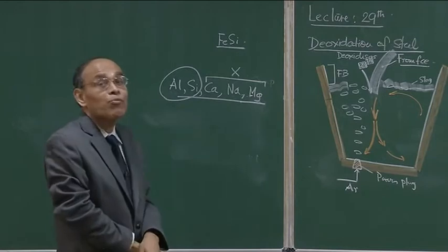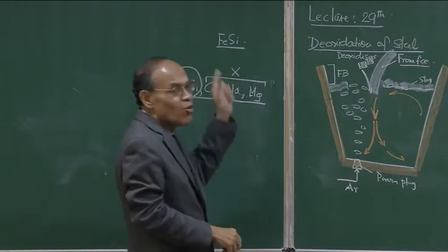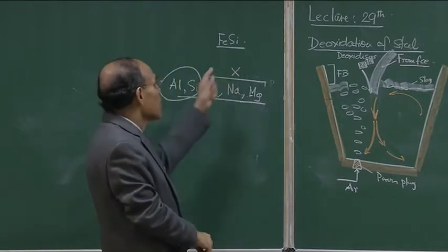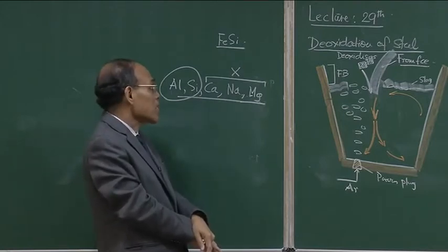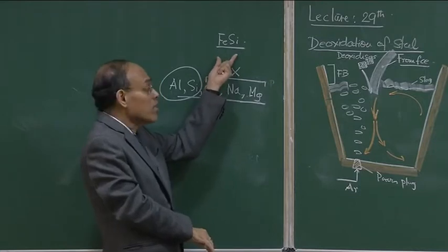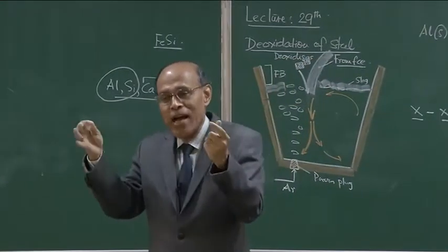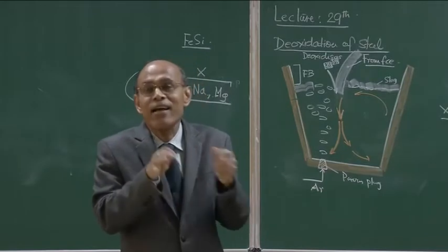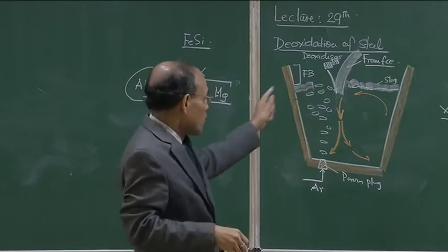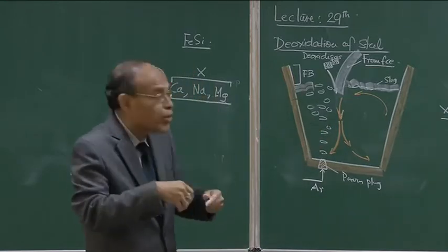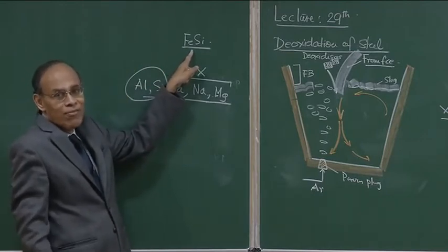You again have high carbon ferrosilicon, low carbon ferrosilicon. Okay. You have to be very careful while adding, because this comes with a lot of impurities also. It can have, depending on how crude the process of manufacturing ferrosilicon is, a significant amount of impurity. Now you are moving towards purer and purer steel. You can see, pig iron had a lot of impurities, crude steel making has lesser impurities, and now you are going to go to secondary steel making or ladle metallurgy, the downstream operation, that will improve the purity. You cannot afford to add an impure material like ferrosilicon, which will bring in a lot of impurities and jeopardize the final quality of steel.